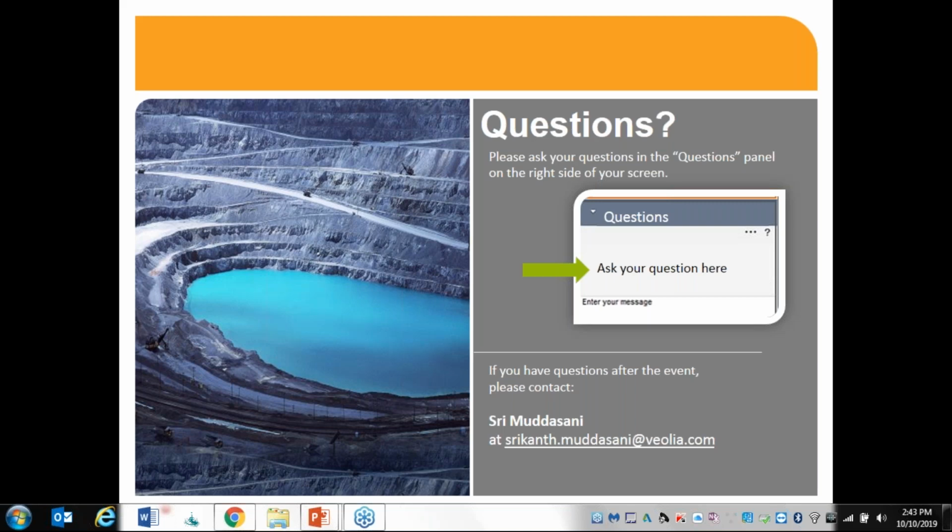You need to add an additional small RO system in order to reduce your TDS. So to answer your question, no, you cannot reduce TDS, but you should be able to reduce your sulfate. It's mainly for the sulfate removal process. In order to reduce TDS, you need an additional small RO system, I'm going to say a bypass RO system, based on your TDS limit.